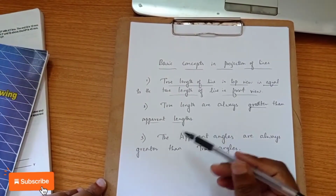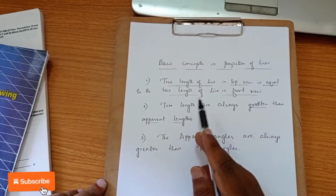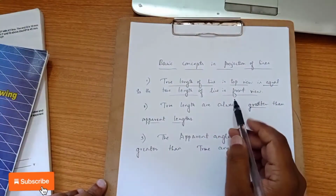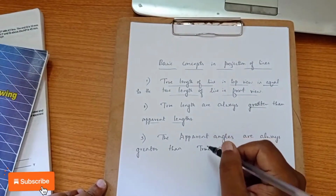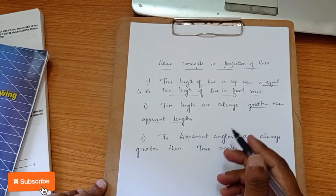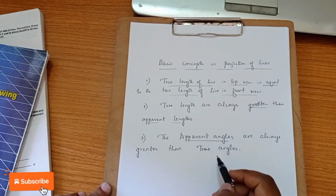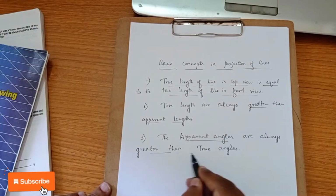As we are solving the problem, we should make sure of these. We know that the true length of the line in the top view is exactly equal to the true length of the line in the front view. That is the first concept. The second concept is that the true length is always greater than the apparent length. Remember it. And apparent angles, which we find out, are always greater than the true angles.